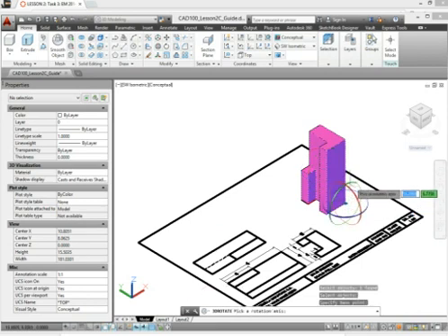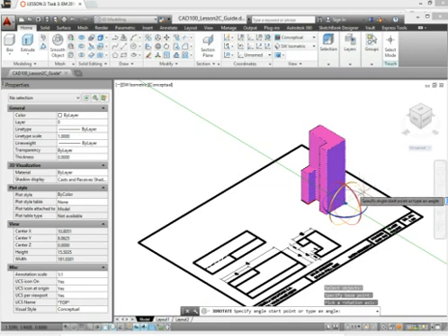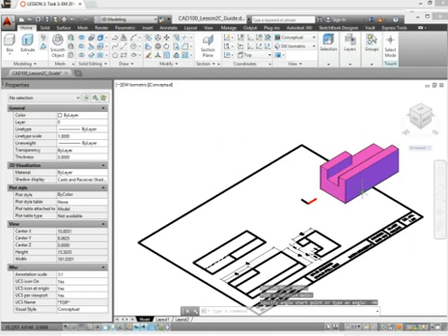After you do that, you need to pick an axis rotation. There's three choices with this command. Let's say I pick the green one here, which is parallel to the y-axis. If I pick that, it's asking for an angle in which to rotate. There is a negative or positive direction depending on the direction of your x, y, and z plane. Currently, right now, I believe a negative number will rotate you the right way. So if I type in negative 90, yeah, it lays flat.